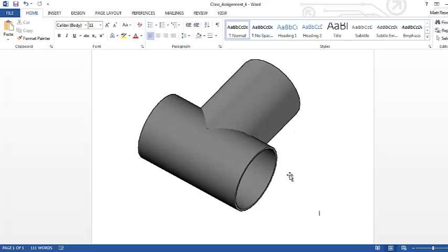So when I look at something like this, I call this one the header. It kind of runs horizontal. And the vertical one coming in, I refer to this as a branch. So we're going to be working with tubing again. I think I've got this one maybe 14 gauge tubing. And really I only need to know the OD diameter to draw that up. This branch kind of intersects that header and will come all the way down to about its center line here, and kind of get these like deep V's that you see on the side here. So this is the one we're going to draw today.